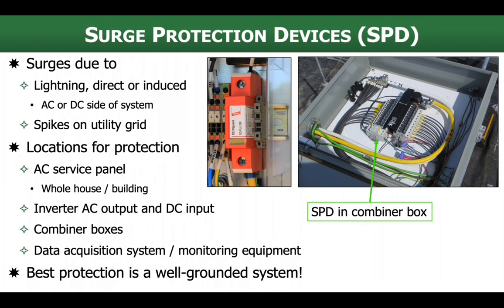The other thing I want you to keep in mind here is this is not lightning protection. Lightning protection systems are a completely different subject. The National Fire Protection Association that publishes the NEC has a whole other standard on lightning protection systems. Lightning protection engineering is a specific trade. There may be times when you need to integrate with an existing lightning protection system on a building. We're not getting into that in this course, but that's not what surge protection is about either.